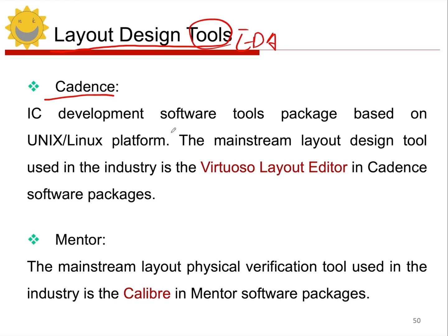So in this IC design platform, there is specifically a dedicated layout design tool, known as the Virtuoso Layout Editor. We use the IC618 design platform, which supports schematic editing, layout editing, and simulation. My simulator is Spectre. For physical verification, we use Calibre from Mentor Graphics, now Siemens, for DRC, LVS, and PEX. Calibre integrates with IC618 for analog design. The software runs on Linux.